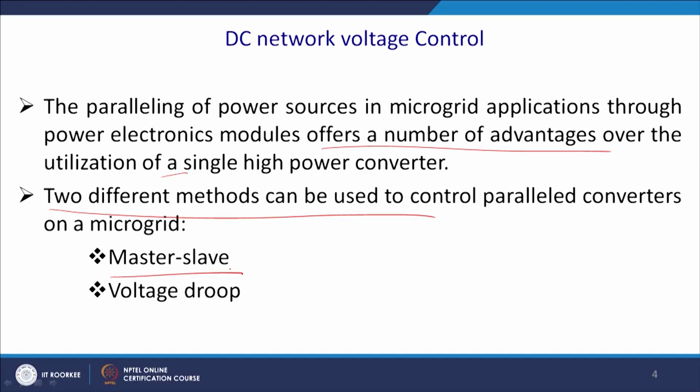And in general, what happens if you have so many small DC to DC converters is that all the efficiency will be less, because you cannot put a huge amount of money into investigating or reducing the losses of a particular DC to DC converter. But if you have a centralized DC to DC converter which has multiple outputs, that is preferred over multiple DC to DC converters.